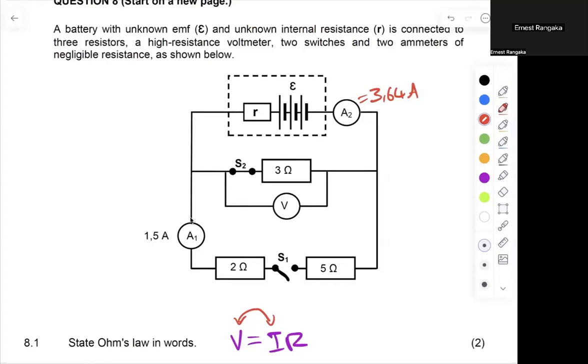Okay, so very, very important, right? I'm getting some good answers there. There'll be no flow of current through that branch, right? Meaning A1 is not going to have current flowing through it. A1 is going to go right the way down to 0. This is going to fall away. I'm going to now basically have 0 amps through A1 because no current's going to flow.